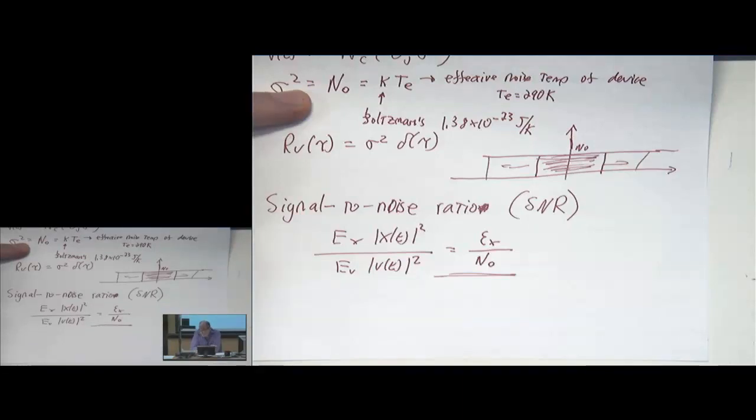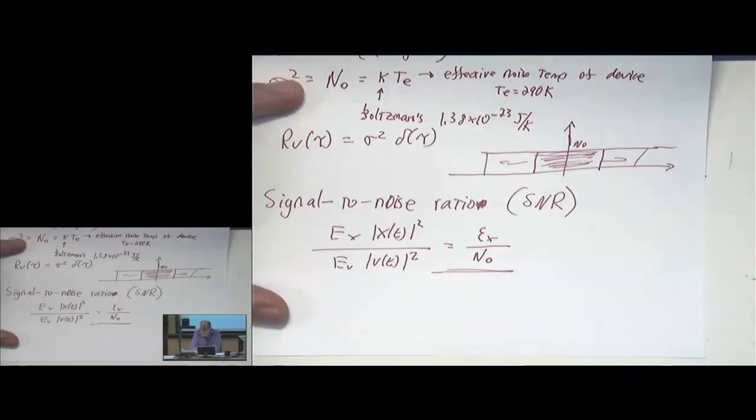Yeah, and the reason is that a lot of this detection theory comes from radar. The difference is that there, you typically want to detect with a much higher probability. If you miss an object 1 out of every 3 times or 1 out of every 5 times, that's pretty bad. But here, it can be okay because we have coding on top of this, and that coding is very powerful. You don't have that concept as much in radar because you're shooting a signal and looking at the observation.